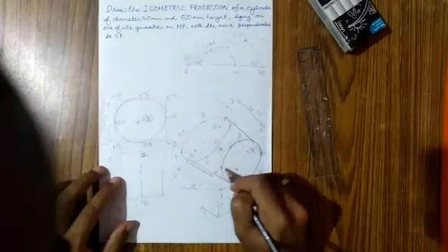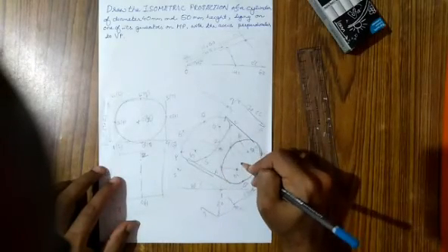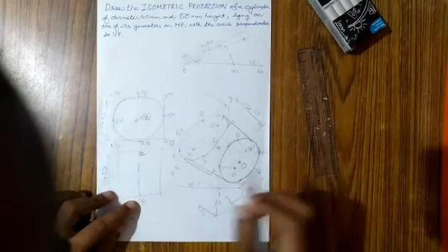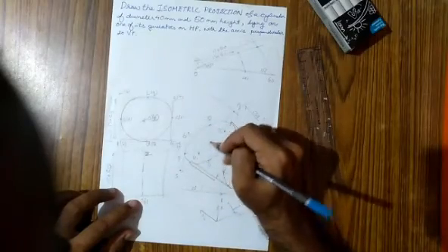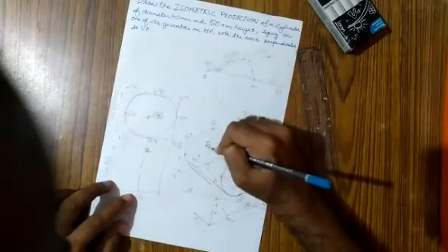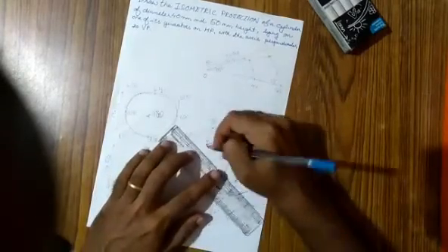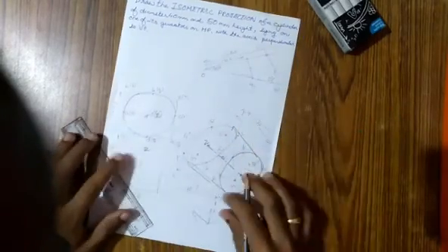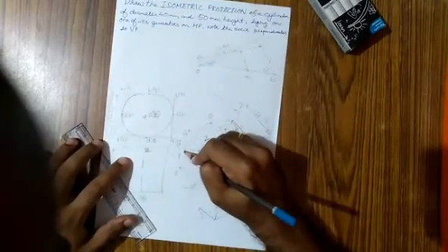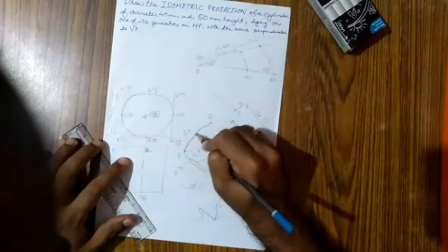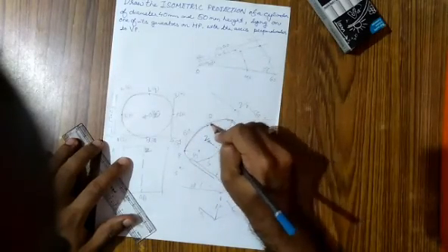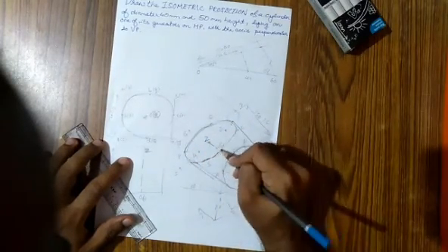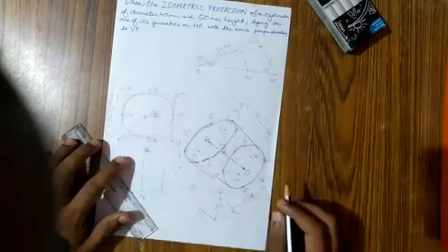So for that, join AC and BD. You will get this center point. This is your point O, and join PR and QS. This is your point Z. You join O and Z. This is going to be your axis. Okay, this is going to be your axis. And taking the back face, this edge up till here, it is going to be visible, whereas the portion at the back is going to be covered. So that is drawn using dotted lines. Thank you.